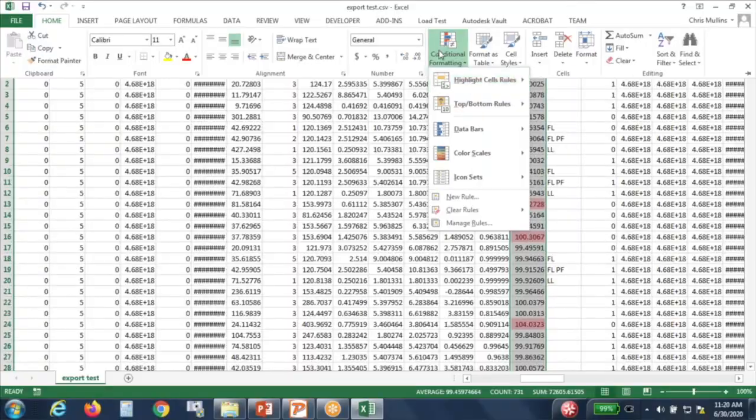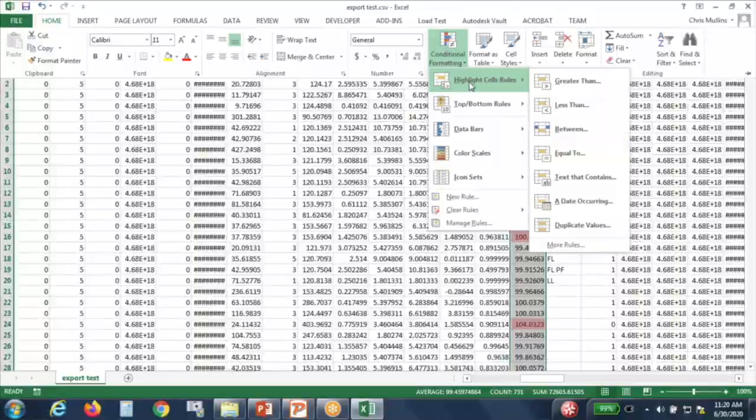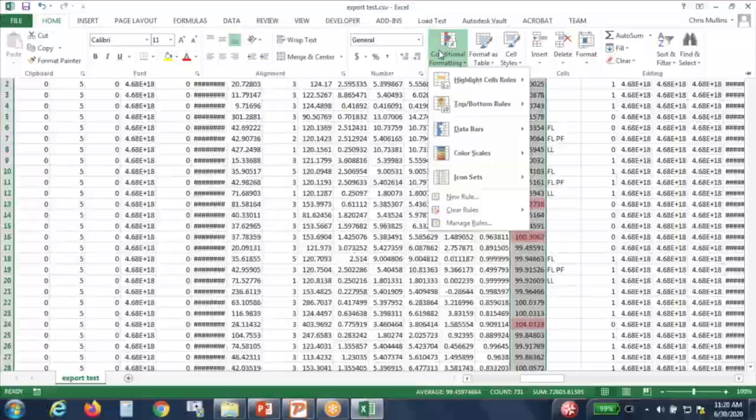The PowerMaster can support both a customer load test and a phantom load test. If it has no label here, that means it's a customer load test, so you were testing the meter under customer load conditions. If it's got a label here, full load, power factor, or light load, that lets you know it was a phantom load test. It's giving you a good designator of what's going on.